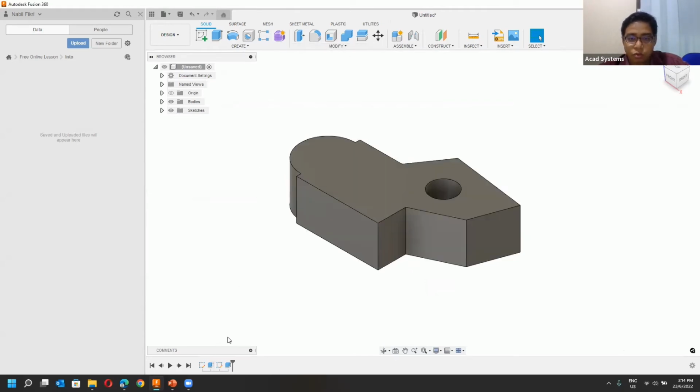Now at the bottom over here, once we have created some things, you will see we have this sketch, and then we have some features from here, which is the extrude. So unlike Inventor, this design tree is actually not put on the left. In Fusion, we have it at the bottom, and the sketch will also not be consumed by the features, right? Like Inventor, Inventor will likely consume the sketch, but in Fusion, we do not have that. But we can still edit it.